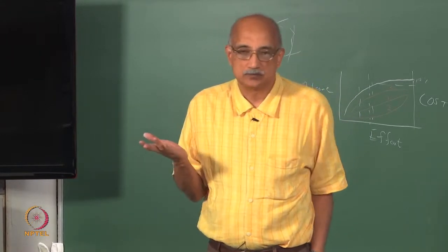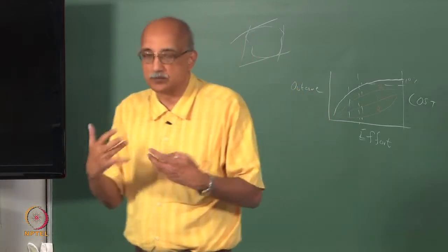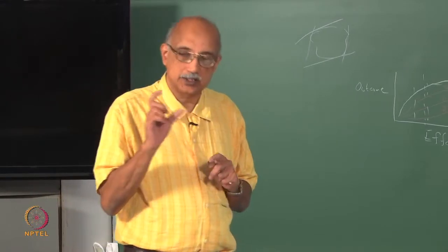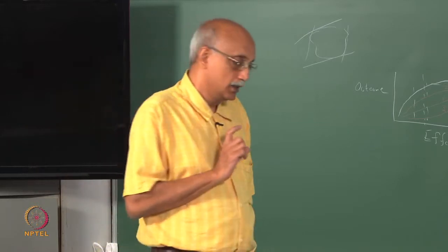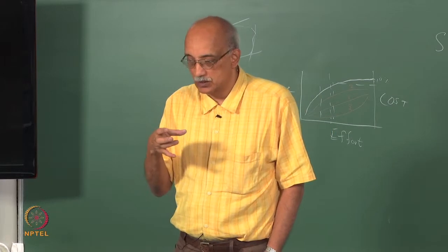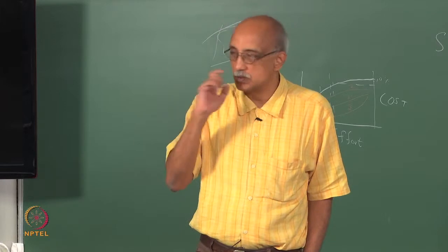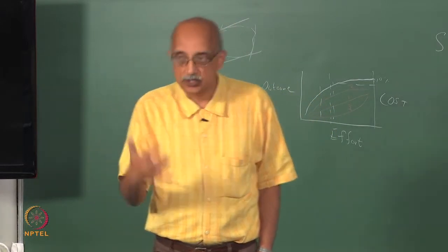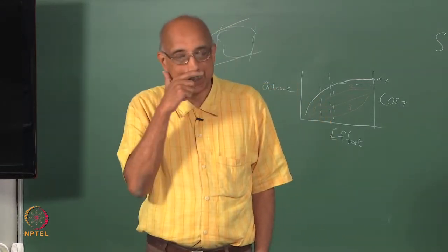What do you think will happen? As you tap, things become more dense, right? They settle and they conform, they fit into interstices, and so the difference in density will be significant, provided that initially the particles were assembled in such a fashion that there was a lot of empty space between them. So, the ratio of density after tapping to density before tapping is a measure of the mean sphericity of the particles in that powder.